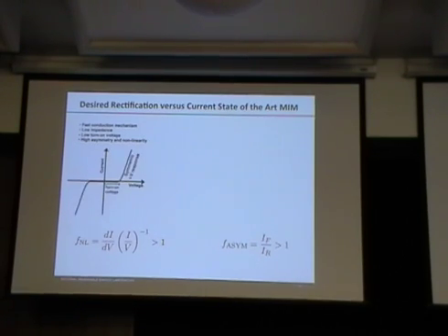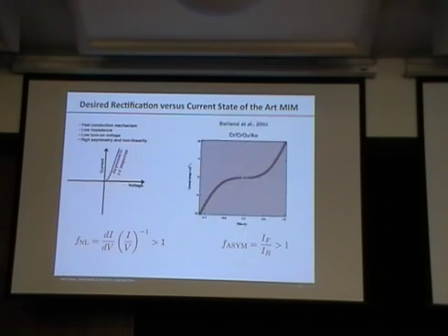And you want to maximize these figures of merit. We don't want to have something that's symmetric. We don't want to have something like this because the turn-on voltage is way too high. And if all we've got is a single photon to do this process with, that's going to be a problem. So we want what we call the nonlinearity to be super high. We want the asymmetry between forward and reverse to be high as well. So we want something like this.